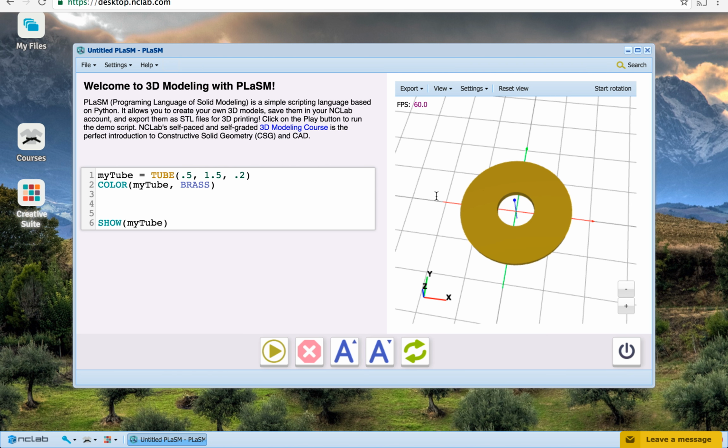The way that we tell the split command which axis we want to cut the object on is that we specify one of the main axes, being one of the x, y, or z axes, and then we tell the command a point on this axis that we want our splitting axis to pass through at a right angle.